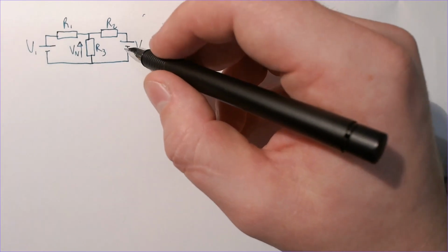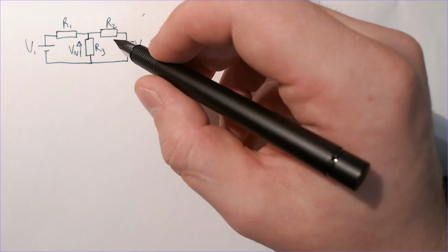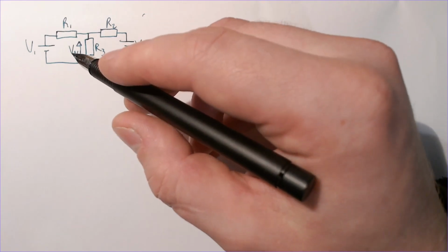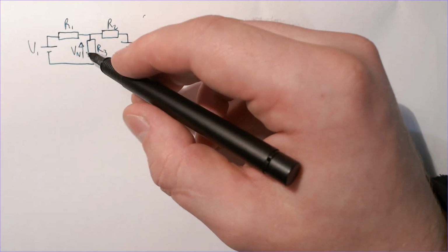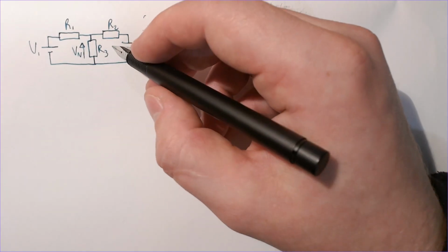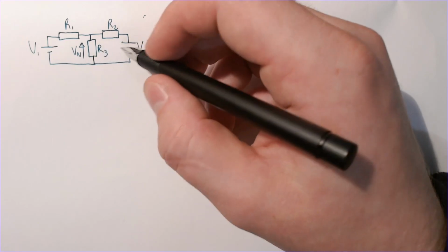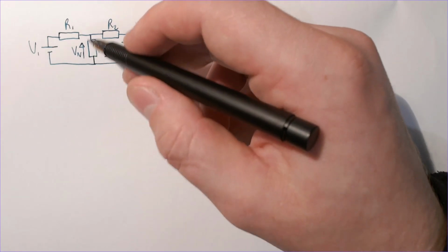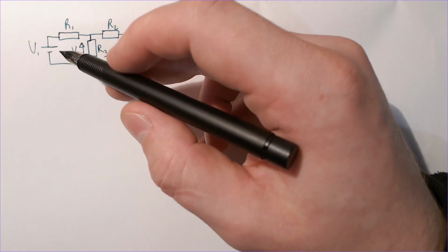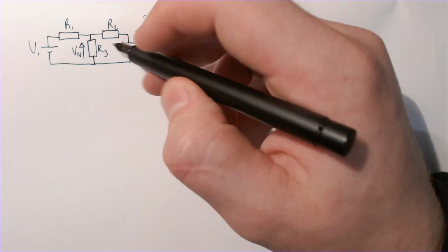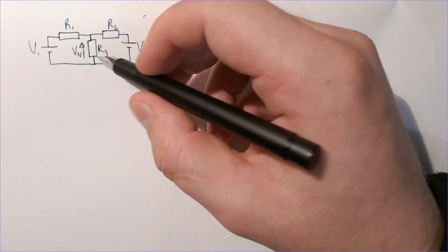And then by doing this for each separate source in the circuit, the voltage or current that's wanting to be found, such as Vn in this example, as was on the previous examples, can be found by adding together the voltage from each of these sources. So it's sort of looking at it as though there's a contribution from this one and a contribution from this one, making that voltage there.